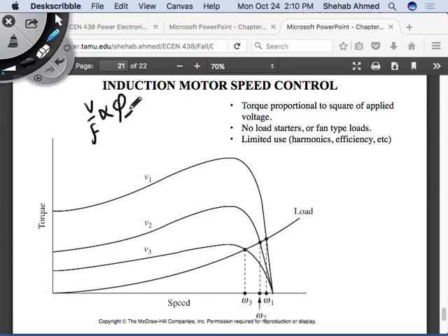So I'm just controlling the voltage. If I'm bringing down the voltage, what am I doing? At the end of the day, the induction motor is an electrical circuit. It's a box here. It's a two-port network with a circuit inside. Right? You bring down the voltage, you'll bring down the current. So it's a way to reduce starting current in an induction motor.